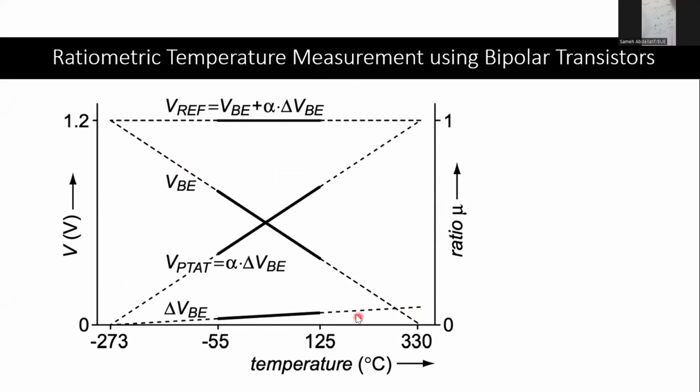So by making the experiment, I just mentioned that this is not a controlled parameter. This is just a measured parameter. So I go to the lab and I measure this variation of the VPE with temperature. Now I have delta VPE. What I can do is multiply this delta VPE by a factor alpha so that the equivalent reference voltage is temperature independent.